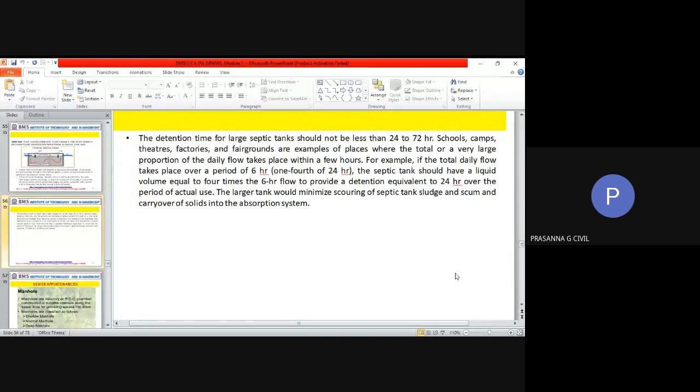So first thing, septic tank is a low cost system. Secondly, why its importance, if you are asked, it is very, very important where unsewered areas exist in cities. Then the only way in which the waste from that building can be taken is through or passed on through a septic tank, and it's a one unit treatment. So that also reduces the cost.